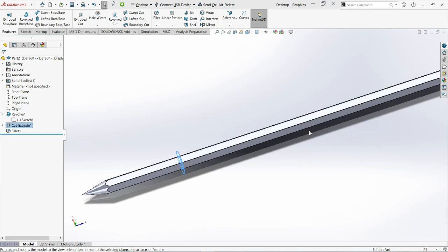The number one thing about Solidworks is just patterns. The buttons are confusing, the hotkeys are confusing. But if you can figure out how to break your part down into its basic shapes, spheres, cylinders, cones, rectangular prisms, these are going to be your tools with which to make your parts.